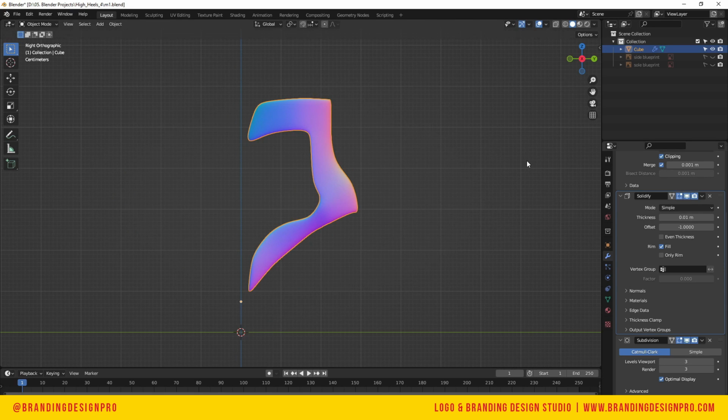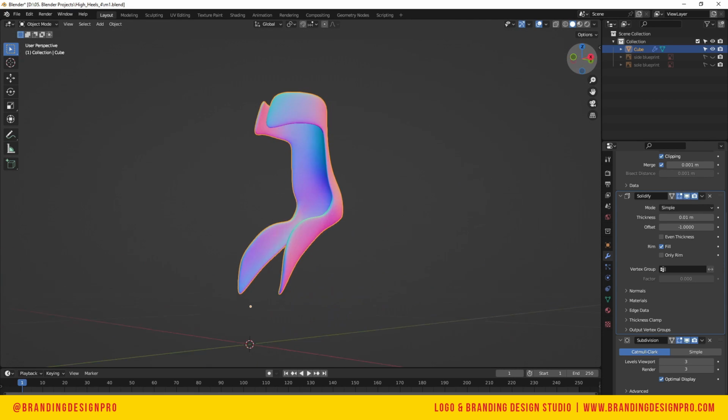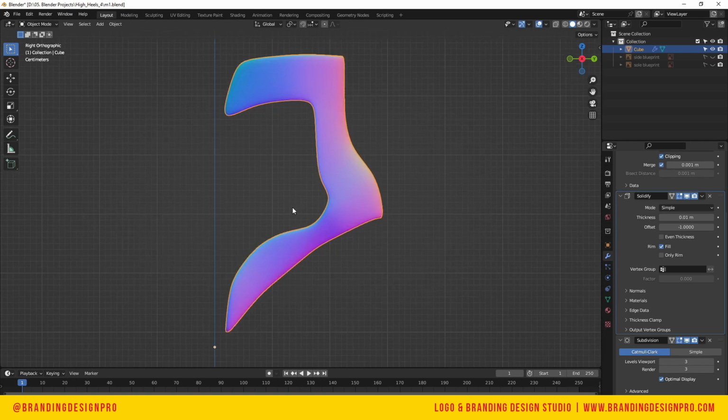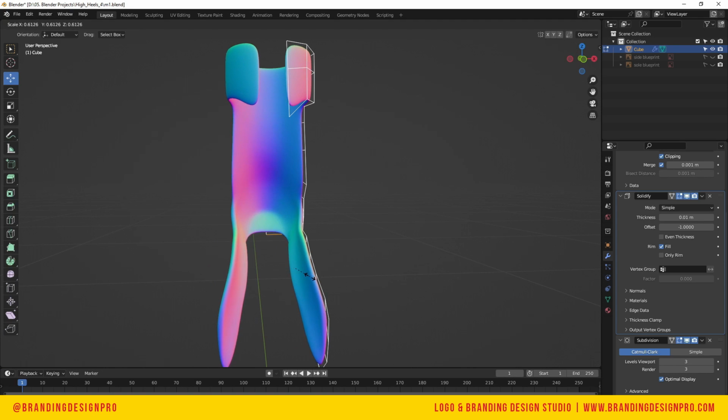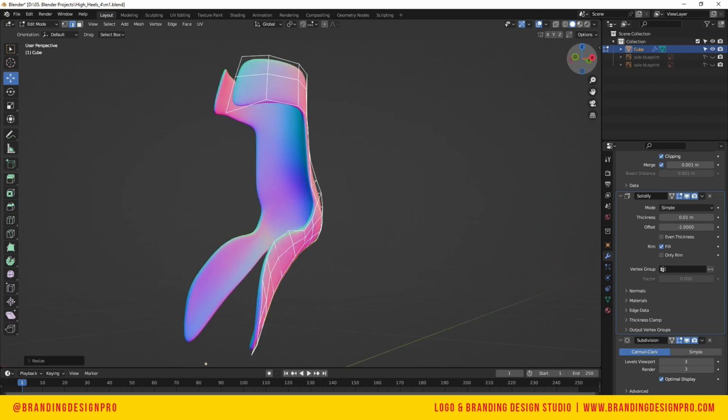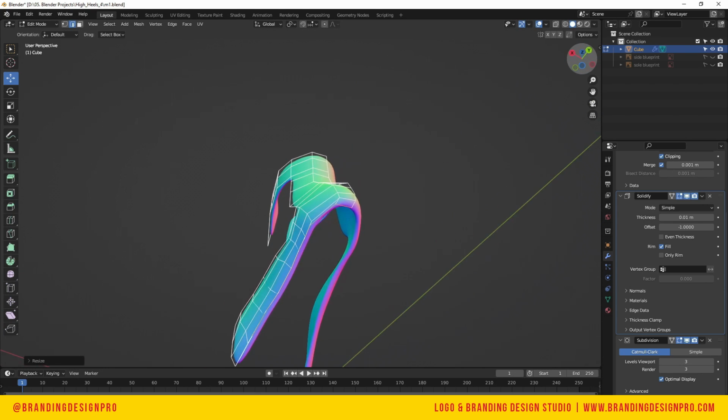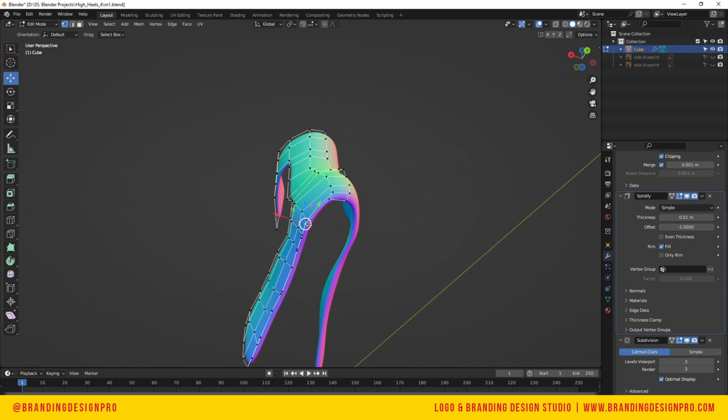Let's look at it. And we're making progress. We're getting there. And we're going to tab in and then select the bottom edges and then ES to kind of scale it. And I'm just alternating between Y, X. And I just ended up settling with Y. And then now I'm going to select the vertices and just hit GX to bring them inward.